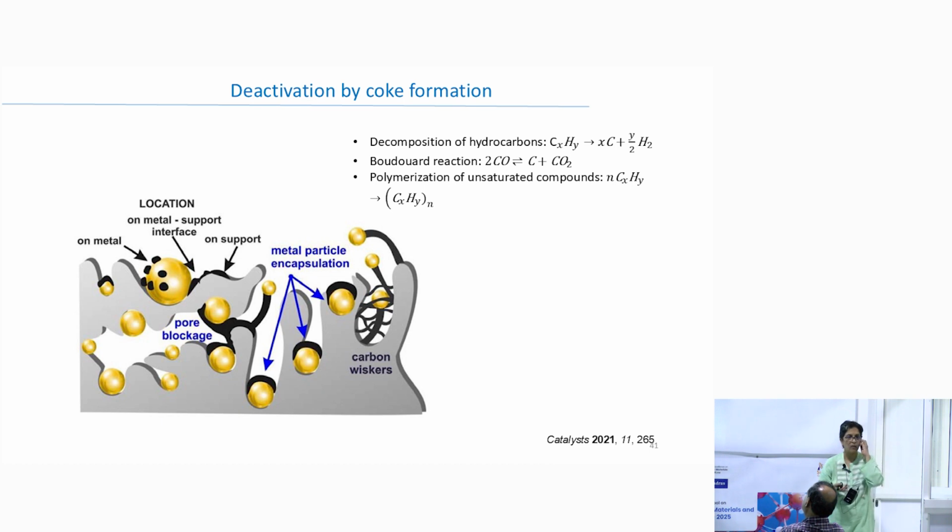People use acetylene and all those kind of things also. So it is just you have literally single atoms of iron in the flow through some precursors, and then on that single atom, the carbon nanotube grows. So if the conditions are correct, if your pressure, concentration, temperature, everything is correct, this forms. This also is quite bad. Look at that. And another thing is that it breaks the particles. So it is called dusting.